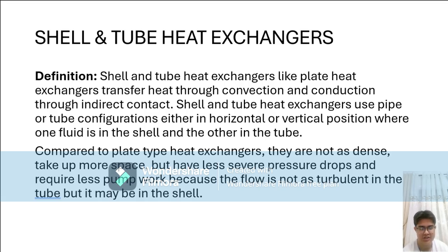This requires that the plates are perfectly aligned and that the rubber gaskets function, and because of this, it creates turbulence, because the working fluids do not flow through a smooth tube, so the flow is not laminar. Because the flow is turbulent, it reduces the effect of a boundary layer that acts as a thermal insulator, preventing proper thermal conduction.